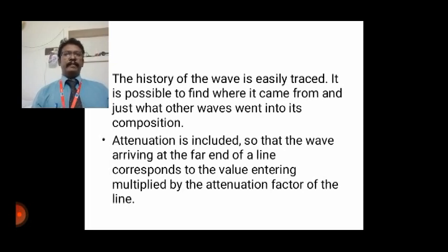It is applied for the study of high voltages. The first point is that all waves travel downhill because time always increases. Finally, attenuation is included so that the wave arriving at the far end of the line corresponds to the wave entering multiplied by the attenuation factor, which gives a clear picture of voltage surges when we have two sections with surge impedances Z1 and Z2.